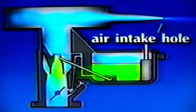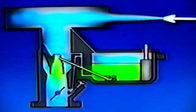The air-fuel mixture in the car depends on the air entering the bowl through 2 vents which open into the air cleaner. If you look at the design of the air cleaner, you can easily see that the air intake hole is relatively small. According to the law of physics, as air is drawn through a small opening, the velocity increases and the pressure drops. A drop in pressure is generally noticeable at speeds above 30 miles per hour. Because the carb vents are located inside the air cleaner, all carburetor adjustments are made to compensate for this drop